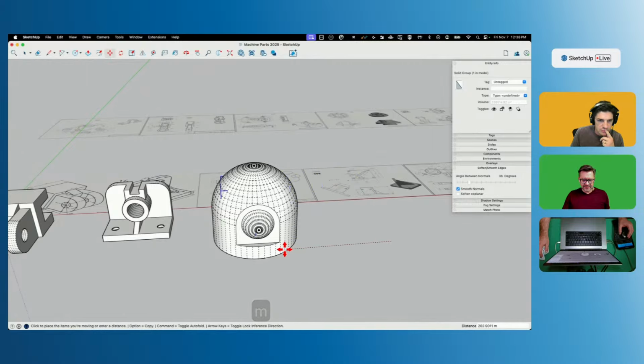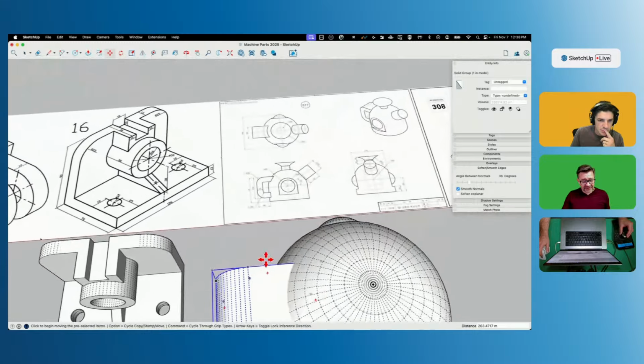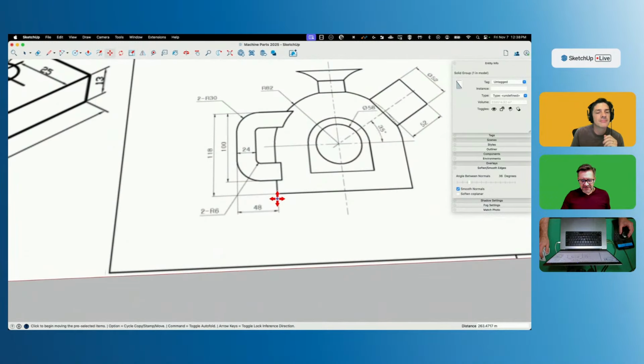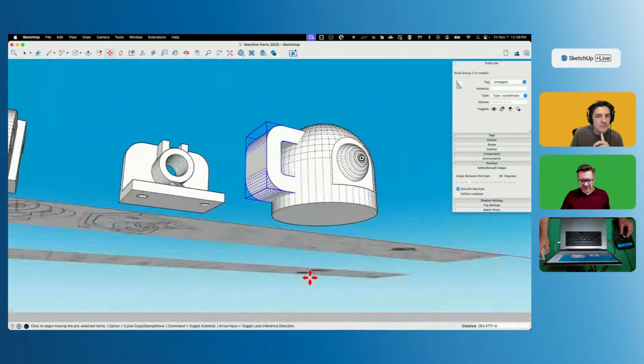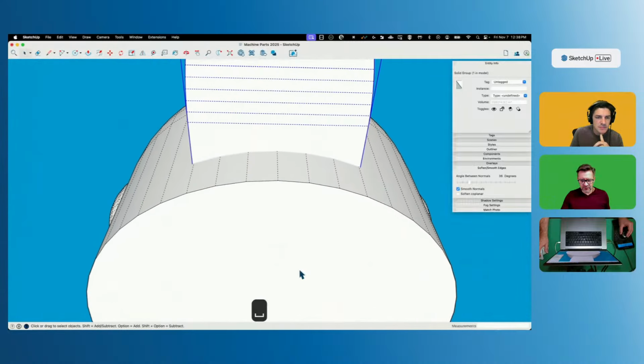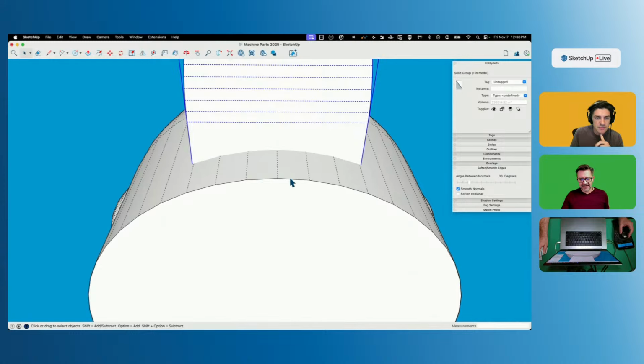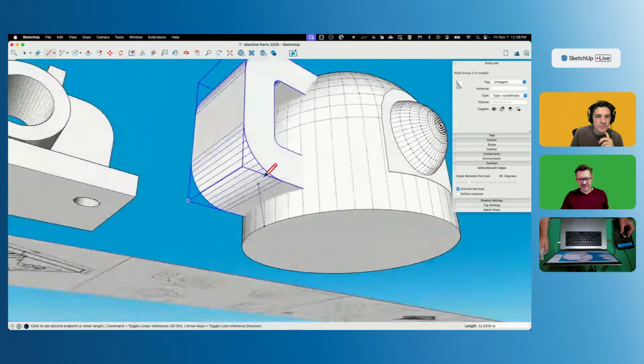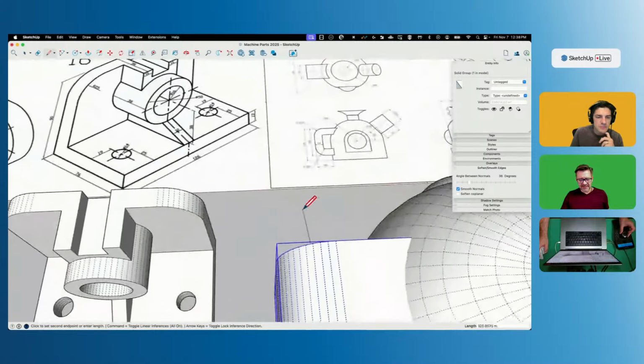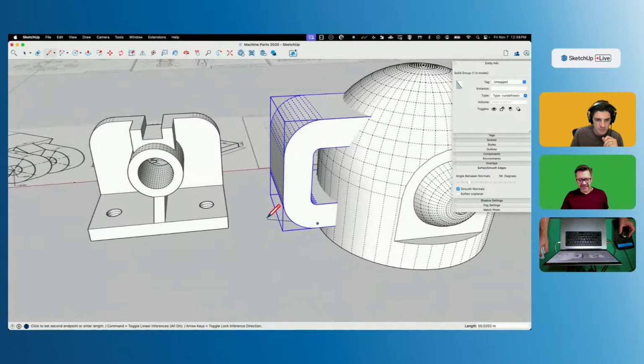Start sliding it on backwards. It's going to sit somewhere over here. Where over here? Well, I'm glad I asked. It's going to be 48 off of the edge. So if I come in here, this is kind of cool. Because I drew this on axis, I can actually see the edges that make up the circle. And I can see there's 1, 2, 3, 4, 5, 6. Since this is centered, that means this point is the furthest outside point. And I could take from that point over 48.